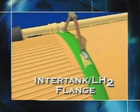Okay, next chart. The inner tank to hydrogen tank flange: we reversed the bolts, and now the longer part of the bolt is in the stringer so that we can get a closeout and prevent voids in that area. We also applied Loctite to the threads to restrict the liquid nitrogen from seeping into those areas. And then we now have a 3-step manual closeout where we can control the process to ensure that we do not get voids as we spray the foam.